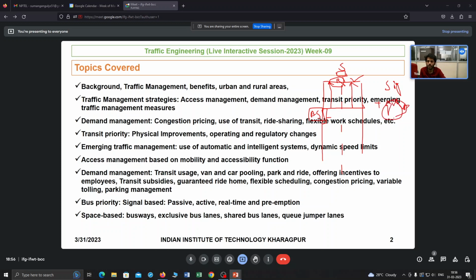So to get rid of this queuing delay, because even if you are giving some kind of signal optimization, sometimes because of the unpredictable dwell time or serving of passengers, it might happen that the bus just joins a queue of vehicles, right? So to solve that, sometimes some part of the lane, or maybe one lane near the intersection, is dedicated.